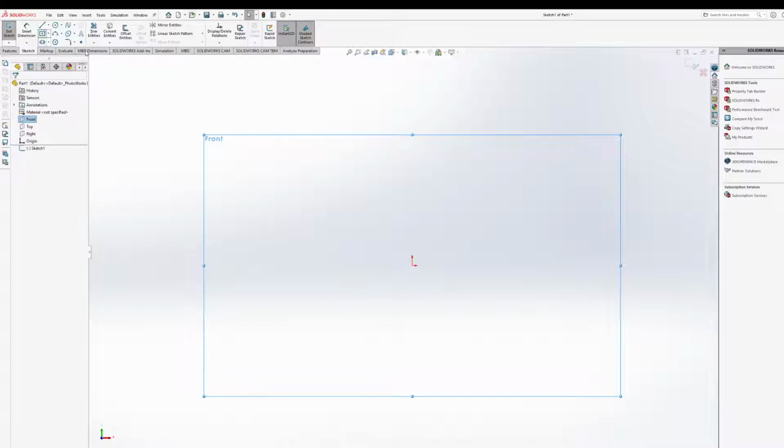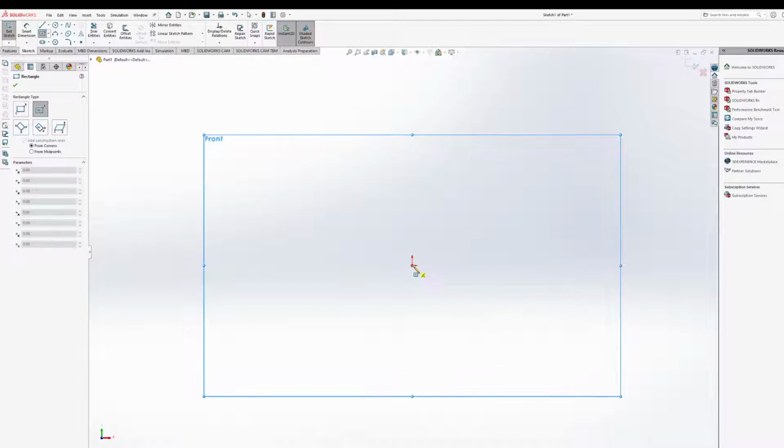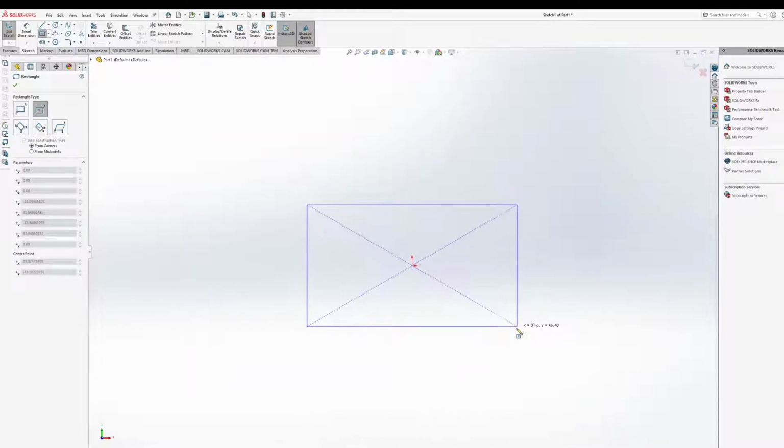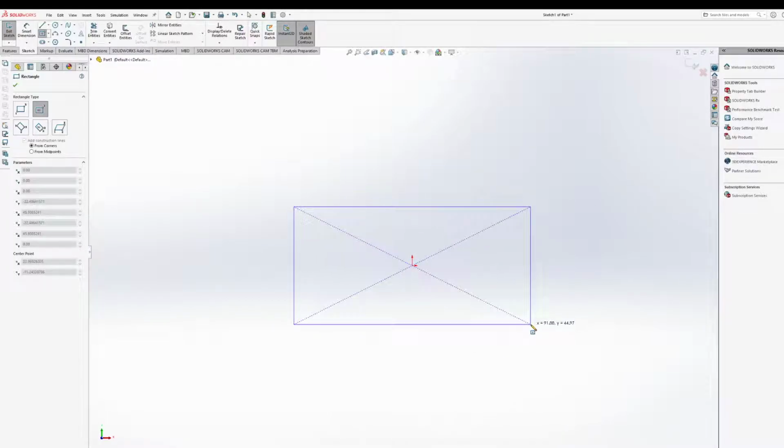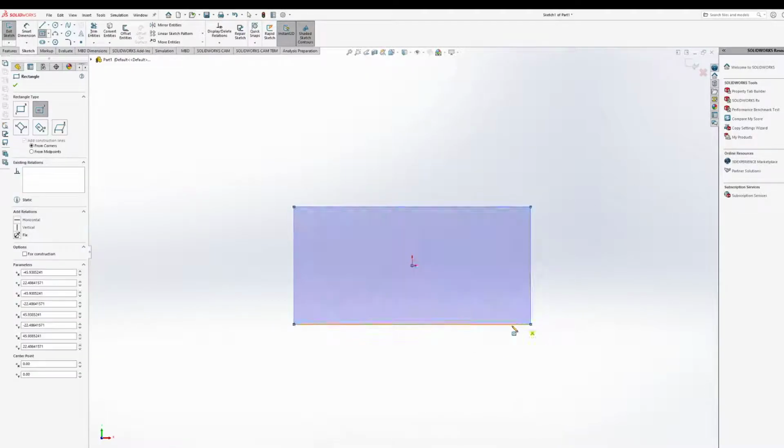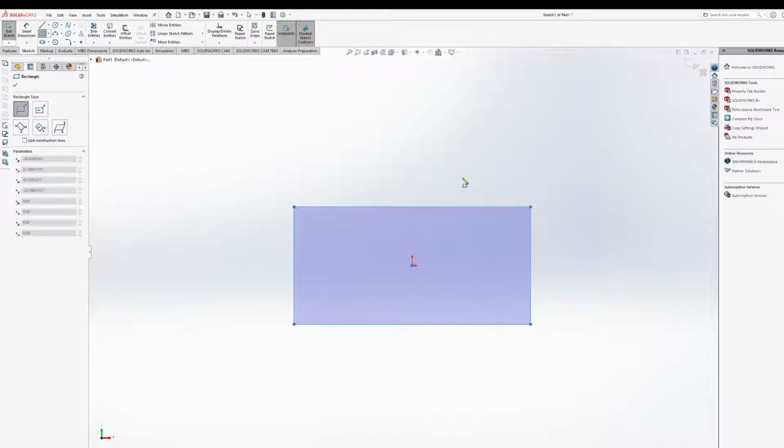So I can go and click center rectangle, and just like I mentioned, it's kind of like a radius almost. Start it at the center, and then we can pull it out and basically indicate the direction in our X and Y coordinates. What's cool is that from this screen right here, it's also indicating that we can choose different rectangle types directly from here. So let's say I wanted a corner rectangle instead.